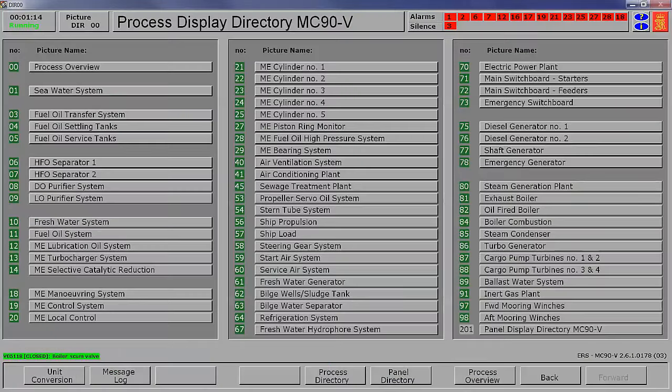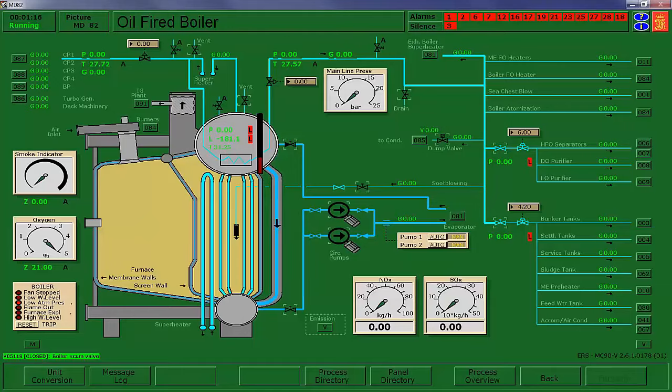So we'll go to the oil-fired boiler. Very important, open the superheater vent. Again though, don't think that will protect you on initial light off, because there's no steam being produced, and there shouldn't be any steam being produced in the first hour.